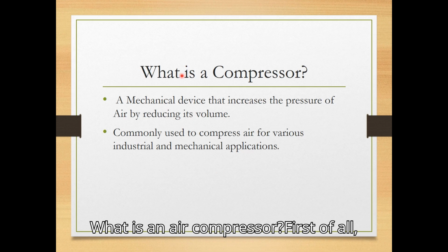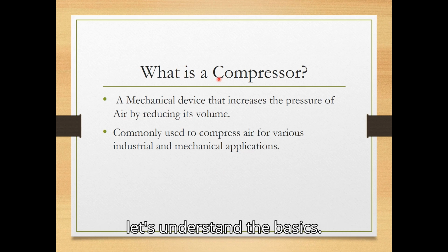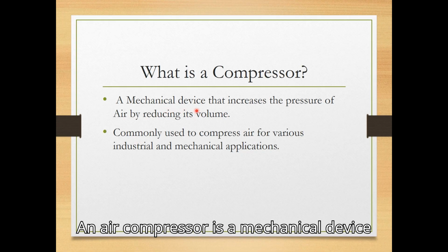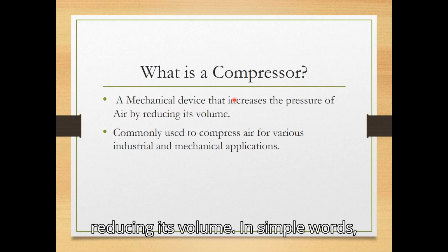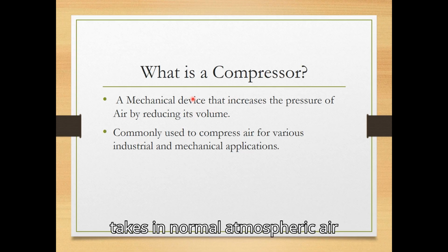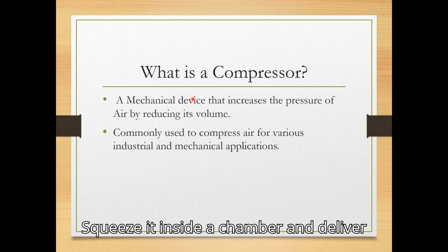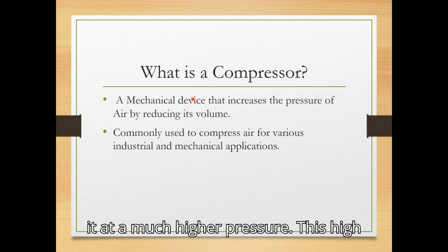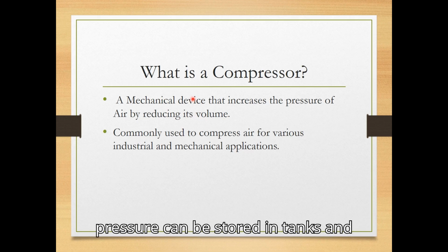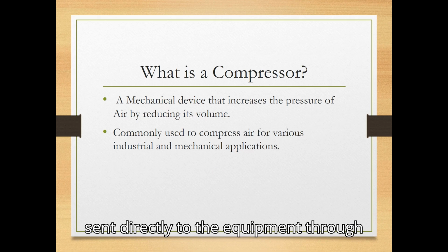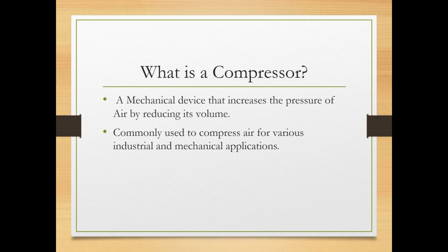What is an air compressor? First of all, let's understand the basics. An air compressor is a mechanical device that increases the pressure of air by reducing its volume. In simple words, it takes in normal atmospheric air, squeezes it inside a chamber, and delivers it at a much higher pressure. This high pressure can be stored in tanks and sent directly to the equipment through pipelines.